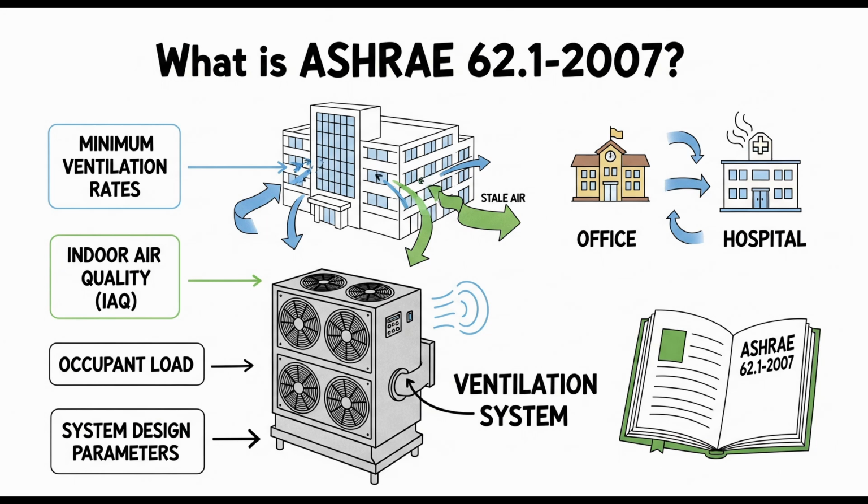We will. But first, maybe the part people see most from the outside, the outdoor air intakes. Section 5.6. Yes. Location, location, location. Yep. This is absolutely critical. The idea is simple. Put the intakes where they won't suck in those local contaminants we just talked about. Makes sense. Table 5.1 gives actual minimum separation distances from potential pollution sources. Okay, give me some examples, like how far away from everyday stuff? All right, think about this. You need to be at least 15 feet away from, say, a garbage area or a loading dock.